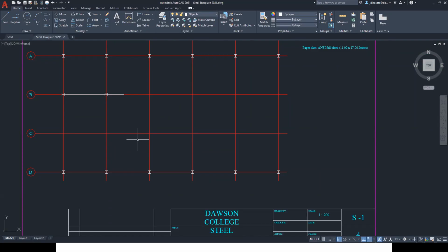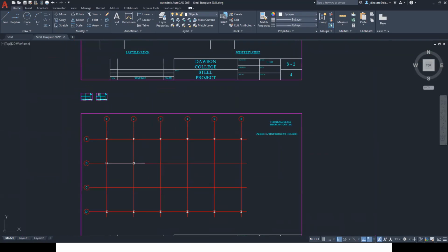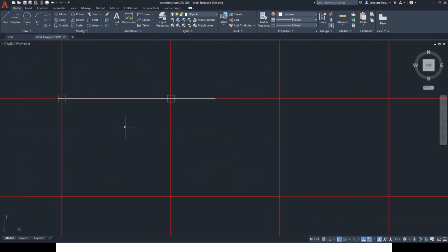For me, the nice thing about AutoCAD is that if I can find symmetry, I only have to draw half. If I find two lines of symmetry, I only have to draw a quarter. So I always look for symmetry. If this thing is symmetric, you can only draw a quarter of it, and then you can mirror it, and it's all done. It's up to you. All I'm saying is that at the end of the day, the faster you can draw with AutoCAD, the easier you are going to make your life. And of course, if you're actually doing it on a job, the more they'll pay you for your drawing capacities. So that's all I can tell you.